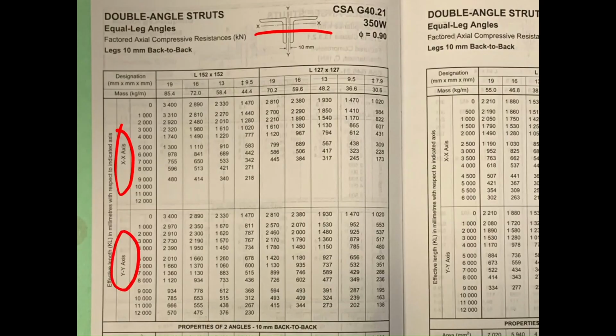in this case they give us buckling for the two axes, because one includes that coupled mode of flexural torsional buckling. And so we wouldn't be able to just use the Rx over Ry ratio here because flexural torsional buckling is more complicated than that, and we can't just fudge the Rx over Ry ratio like we did for wide flange sections. Okay, so to summarize briefly, we have lots of different tables.